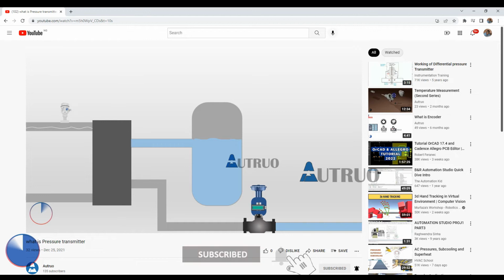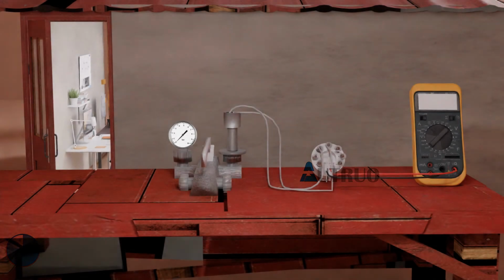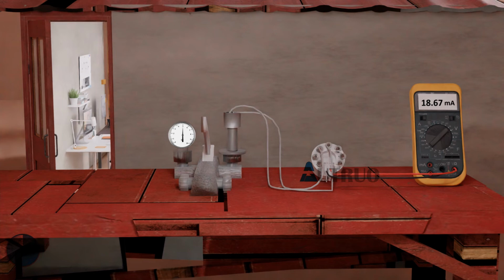So the current signals will be gotten during measurements and calibrations. At 0 bar, the current gotten is 3.4 mA. At 1.25 bar, the current gotten is 4.1 mA. At 2.5 bar, the current gotten is 8.67 mA. At 3.75 bar, the current gotten is 13.45 mA. At 5 bar, the current gotten is 18.67 mA.